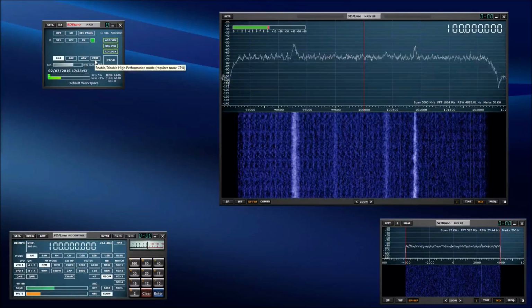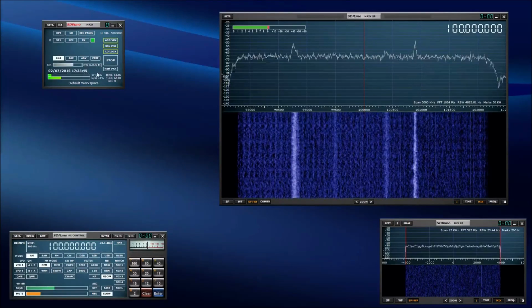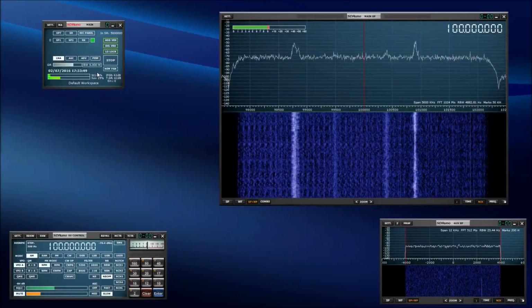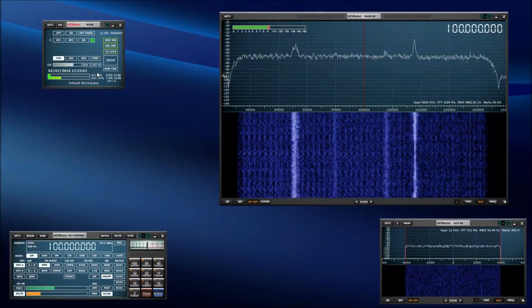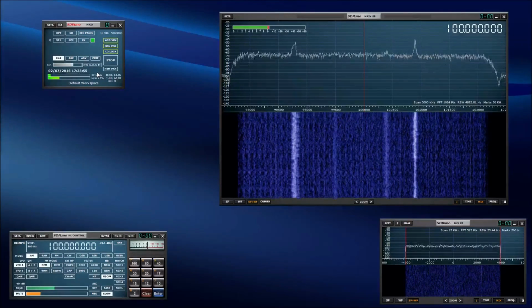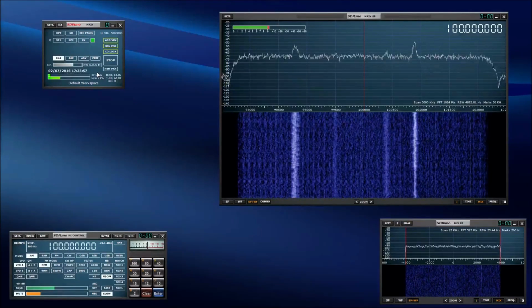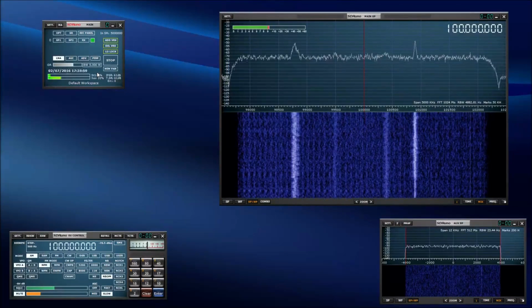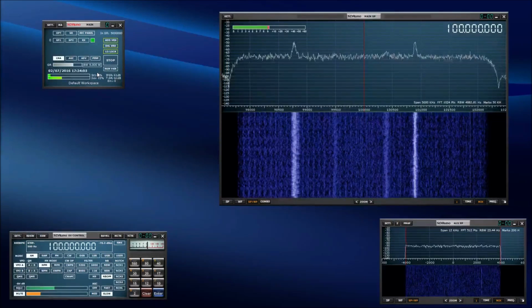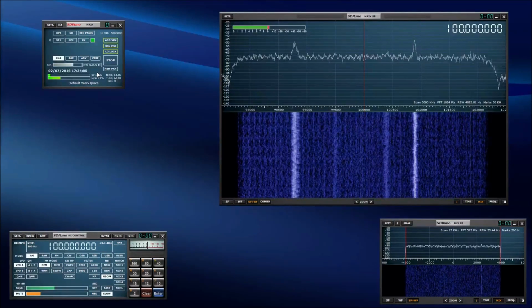We may remove it, we may leave it in there. I'll just briefly explain what the purpose of it was. For any given IF bandwidth of the RSP, there is a minimum allowed sample rate and a maximum allowed sample rate. For the best noise performance, you really want the highest sample rate, but that's obviously more CPU performance.